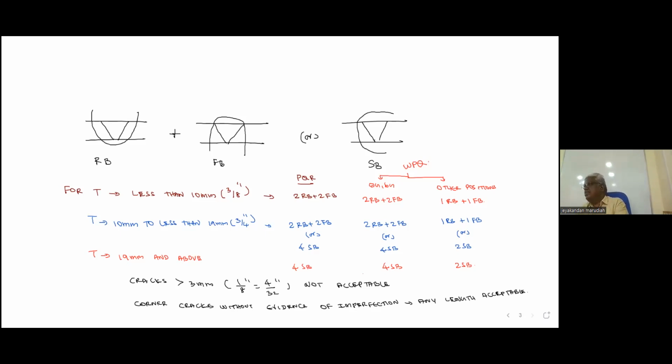The hardenability definition is depth of hardening by quenching. How much depth it is hardened. So hardness is the surface property. Hardenability is the entire thickness property. Third difference is, hardness you can improve by adding carbon. If you want to improve the hardenability, you have to add chromium, molybdenum, vanadium, not carbon.